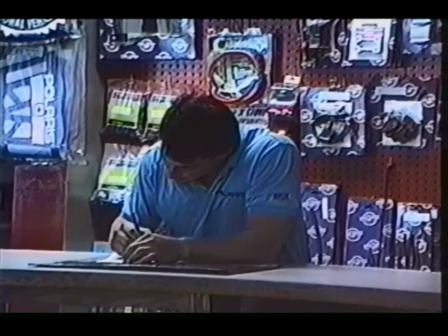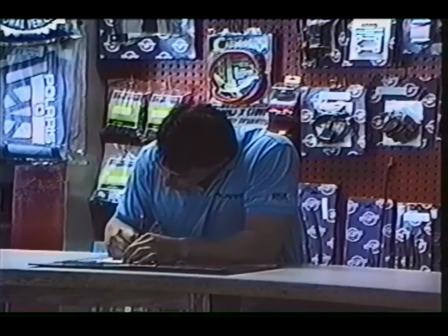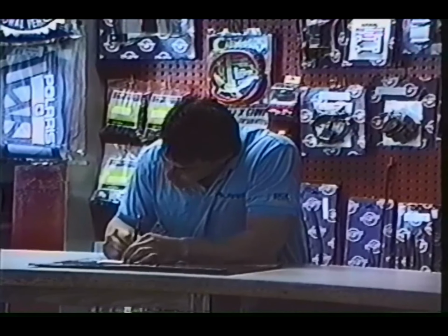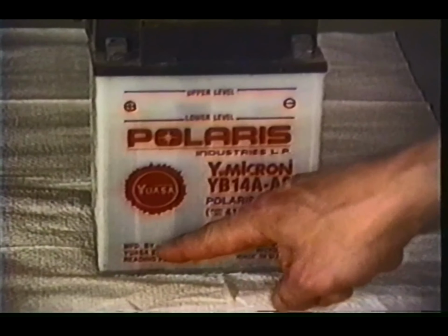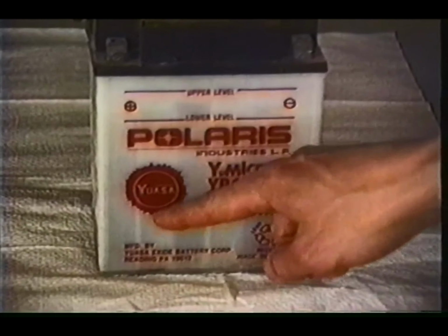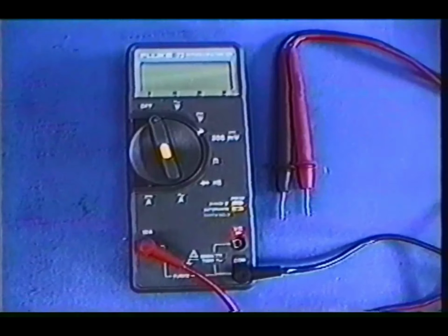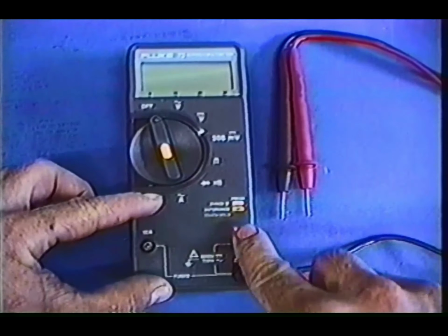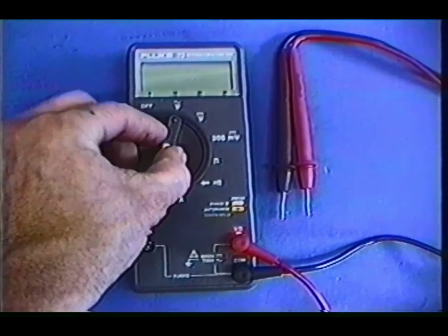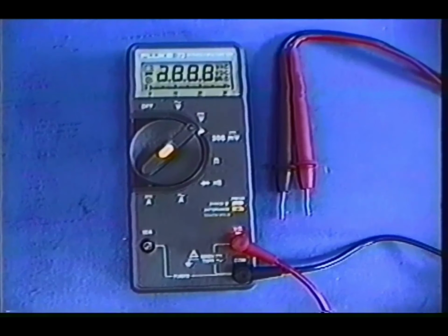Once you have a good idea of what you are looking for, you can begin diagnosing the problem. If the customer says the battery is discharged, inspect the condition of the battery and the connections. Check for signs of sulfation, which are white cloudy streaks in one or more cells. Use your meter and test the battery voltage. We recommend the Fluke 73 digital multimeter. It should give you the same results as listed in our technical specifications.